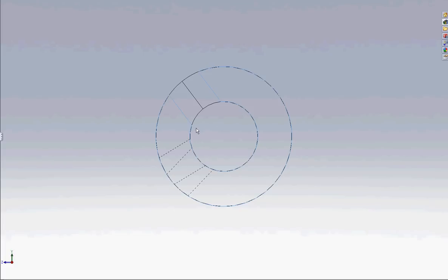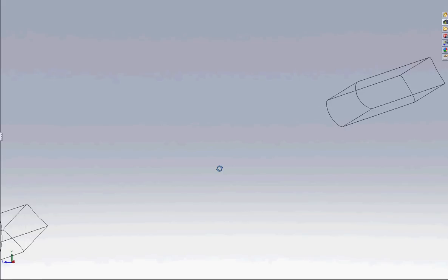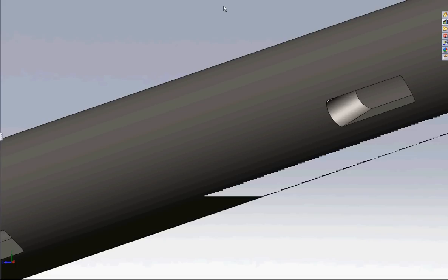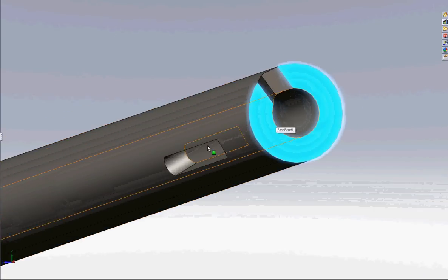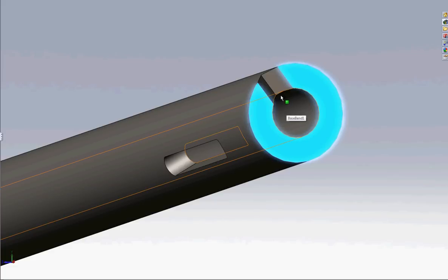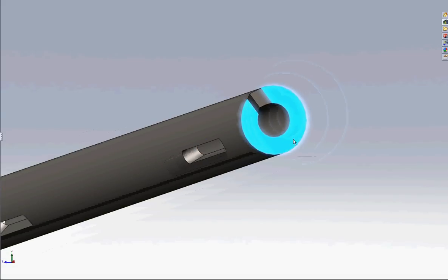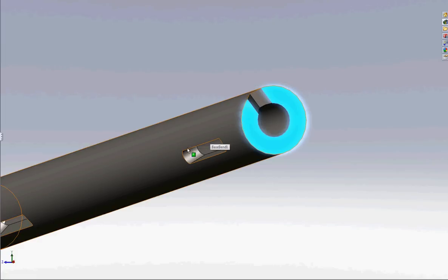Now, if this was a thinner walled tube, if it was half this wall thickness, and incidentally this is a 1/4 wall. It's a 1-inch 1/4 wall tube, and we're putting a 1/4 inch slot in there. So we've got, on the numbers, an 1/8 inch on either side of that cut, but it's just not enough room to get rid of the laser slag. So you can't really cut this in quote-unquote XY mode. You're going to actually spin the tube to get the cut. So instead of using the Y axis, you're going to use the A axis and spin the tube.